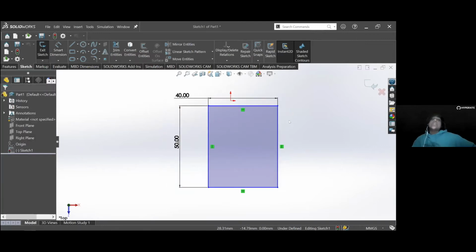So why is it still blue, right? I've added dimensions. Okay, well, now you need to give this box a location within space. You need to give it some reference to the coordinate axis. So here's your little representation for a coordinate axis. When I hover over this, I get this little orange dot, so I can click on that.